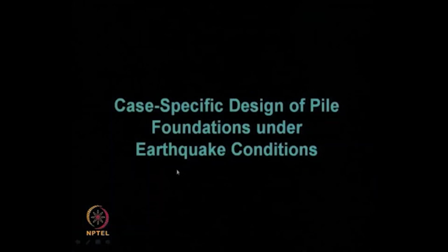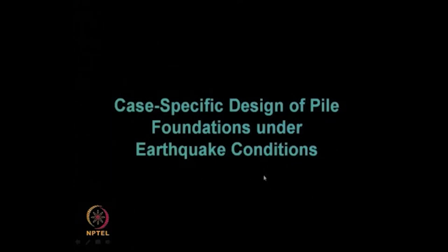Now, let us come to a case specific design. Why am I telling case specific design for pile foundation under earthquake condition? As I said already, it is also recommended by earlier researchers like Professor Poulos that for pile foundation design, a ground response analysis is a must, because you should know how that local soil is going to behave under an earthquake condition, which is supposed to come, or from the past history earthquake data you can provide at that soil condition, knowing the local soil site condition.